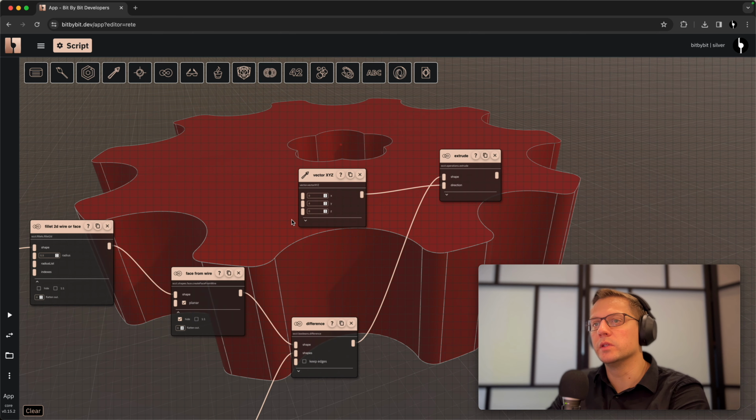It's a bit technical, but you don't see here the object properties or anything. You apply various methods on top of these shapes in Bit by Bit instead of doing sort of object-oriented programming. So here you're doing operations on these shapes, and now you have all the edges, and what we want to do is filter out only the edges that are these ones.